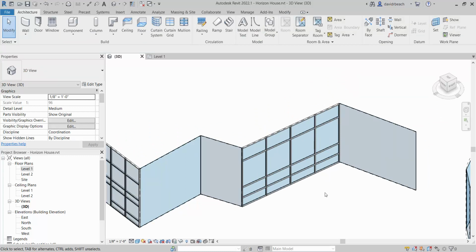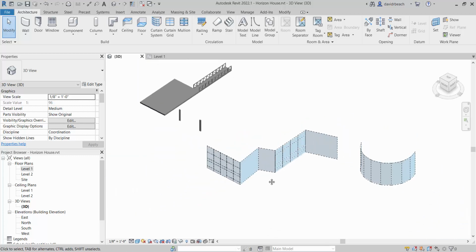Okay? And again, in terms of fabrication, I can isolate the mullions, save them out as a stereolithography file, as an STL file, have the 3D printer draw those flat, and I can really quickly make a model out of these things as well, because it's going to print those dudes flat. I mean, that's like a 2-minute print to do that window at a 16th inch scale. Super, super fast with 3D printers, okay? So it's a really, really great tool, both to build virtual models and to build physical models, all that stuff.